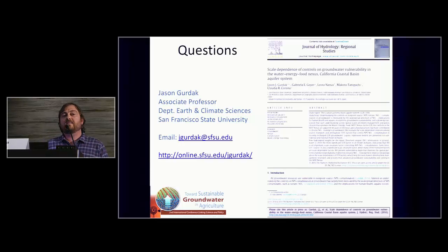Yeah, so I think the dissolved oxygen should be measured when the water quality sample is taken and when the nitrate is measured. Generally, in these deeper aquifers, I wouldn't expect large wholesale changes in the redox conditions over time. I don't think it's as dynamic as maybe some of the systems you work with in the Netherlands. But I would definitely measure nitrate, DO, and the whole suite of the redox indicators when you're there in the field. And second part? That's okay.